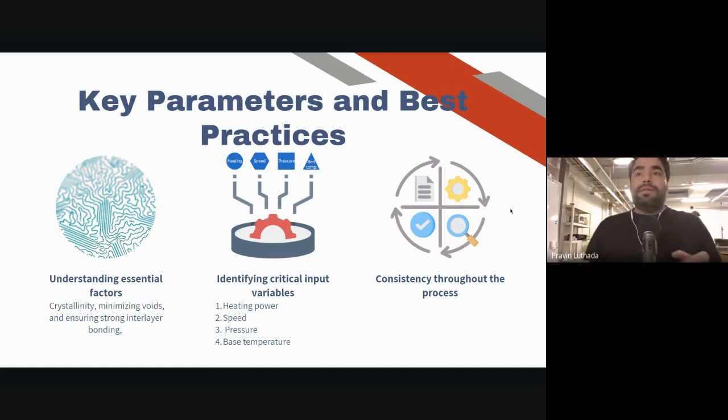So you're trying to combine all these factors, and you can definitely have a secondary process to make sure that you can run your preliminary process of creating a close to accurate preform. But then you can also get an in situ consolidated laminate. It is very challenging. And if you have to take something home from this whole presentation, I would say focus on these four parameters: heating, the speed combo, and definitely the pressure and the bed temperature.